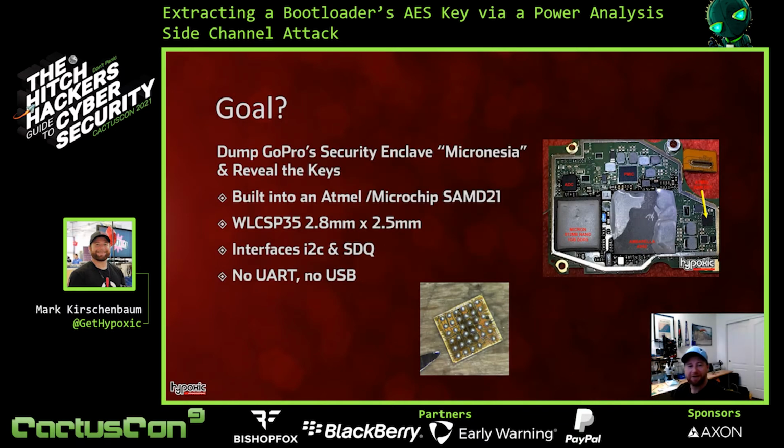Our goal at the end of the day is to basically dump the security enclave's contents and hopefully reveal the keys that are used to do this TPM. We found out after taking apart the camera that it's based upon a Microchip ATSAMD21. That used to be Atmel, so I use those names interchangeably. The part is very small. It's 2.8 millimeters by 2.5 millimeters.